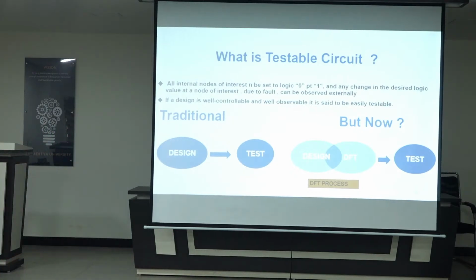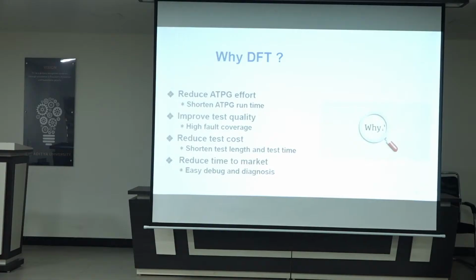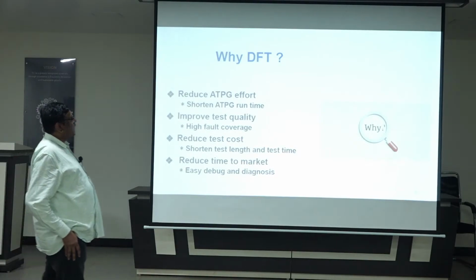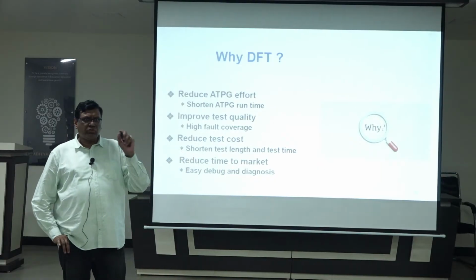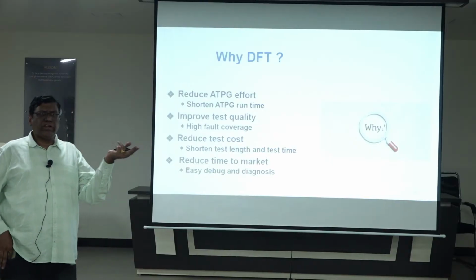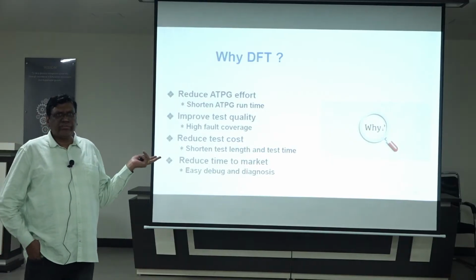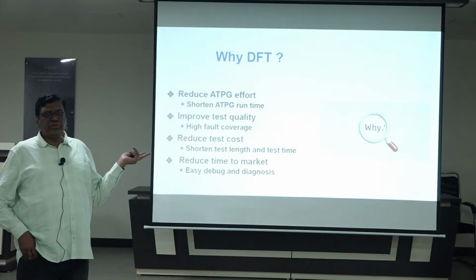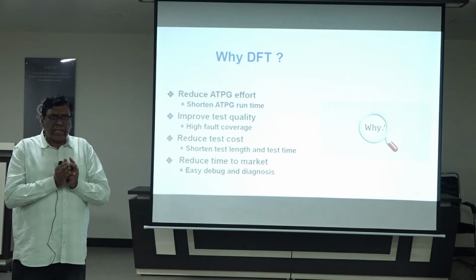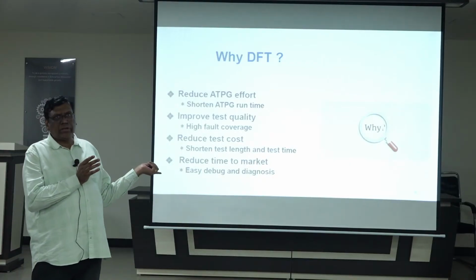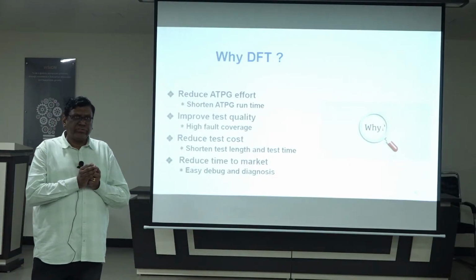Okay, next. Why DFT? Main DFT is used to reduce ATPG effort. That means just now in the example we have seen, for a small circuit we have about 28 different checks to do. So that's a very huge number. That number of test cases should be as small as possible. This DFT can do it. It can reduce the test cases.